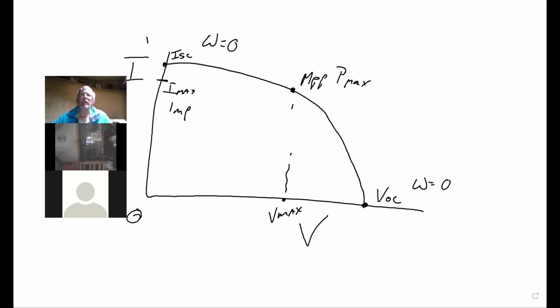All right, so basically this is your IV curve, and you've got the numbers that we're worried about: the ISC, the theoretical maximum amperage, and the theoretical maximum voltage. We use the VOC because when we're designing our systems, remember that in a residential system, the maximum voltage is 600 volts. So we'll use the VOC for that.